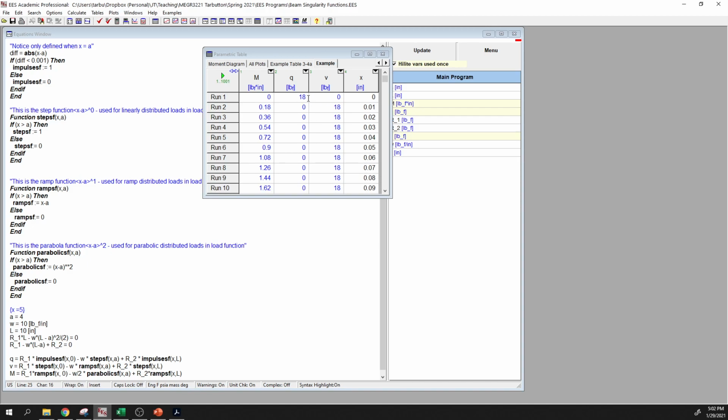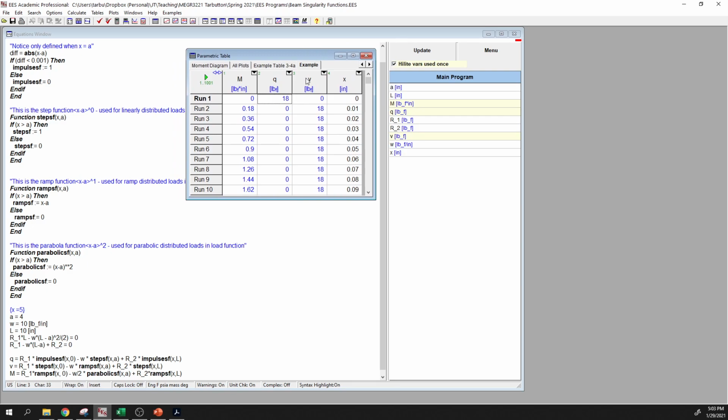So this is pretty interesting. So we can see that our shear, our loading function is defined right at 0. And then right after that, we have our shear that starts. Okay, and then our shear goes and then all the way until some value when we have that distributed load that's a negative, that causes that negative drop, and it creates a negative shear. And then it goes all the way up to our reaction force, okay, which is equal and opposite to the force that's on that reaction. All right. So then, if we want to plot this data, we can.